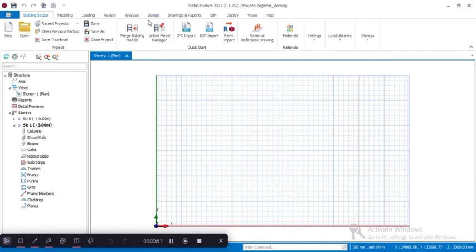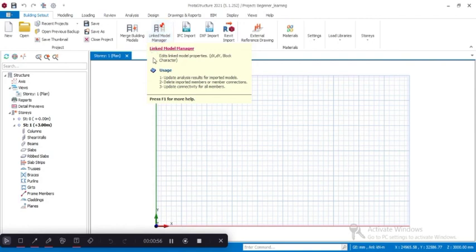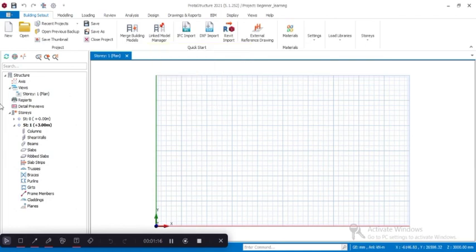Alright. So to select multiple entities, hold down the Control key while you pick them. Left click on an entity to select the entity. Selected entities are also highlighted in the structural tree. Alright, then you can select entities directly from the structural tree. But we don't have anything here, so you won't see that. You'll see that as you continue to go.